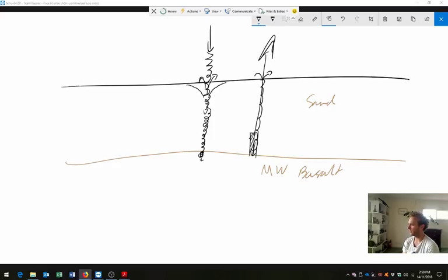So, for the A17, which exam I wonder is, if we do not choose the tank, how should we deal with storing? It's hard to dewater. Yeah, Coode Island Silt is hard to dewater. Look, sometimes it just gets wet and we just have to deal with it. I mean, Delta Group has been working with Coode Island Silt down in South Melbourne, and what they do is if they get a big pile of wet Coode Island Silt and they can't dewater it in time, which is frequently the case, they'll excavate it out and spread it out on the ground and let it dry a little bit before putting it in the trucks to take off site. So it's a problem, but it's something that can be handled. I don't think that probably answers the question on the exam though. I'm not 100% sure which exam you're referring to. Maybe post it again later on. I'll hopefully get to it.